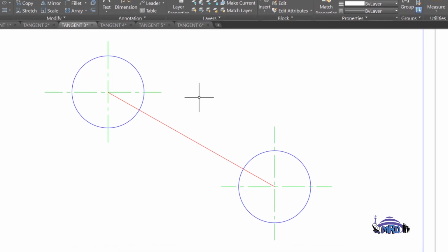This is the one that really would not be applying the Pythagoras in the same way, because all you would need to do to complete this construction, once you've connected the centers, is that you will produce a 90-degree angle to that center line, that connection line in each of the circles. And we know how to produce a 90-degree angle. We know how to construct 90 degrees. That's something that we would have done right at the start of technical drawing. And in CAD, you should also then be able to pull a line at right angles to this.